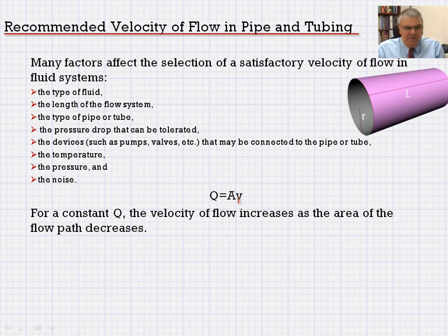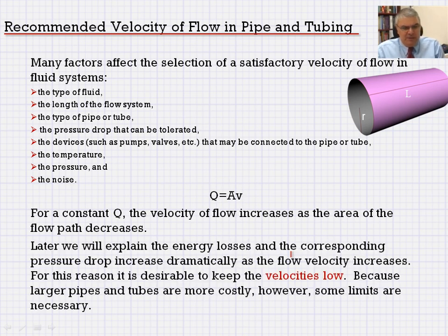For example, if we increase the velocity, and we have to have Q constant, of course A would be lower. So the cross-sectional area through which the fluid flows would be less if we are increasing V, because we need to achieve constant Q. Same results if you want to change these parameters and do a little parametric study.